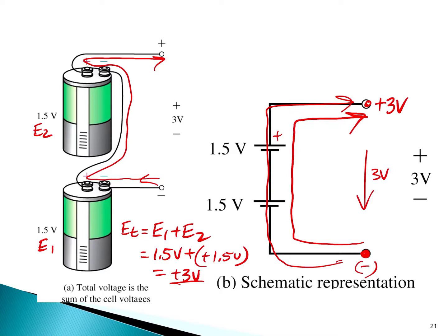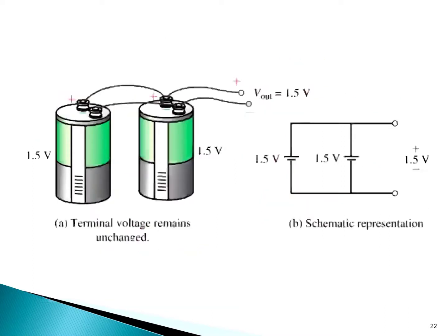Whenever you take a single battery and connect it with others, this is called a battery bank. This battery bank was a series connected battery bank where I used the series connection to increase the voltage value. Now if we think about current in this case, the current would all be the same. So that's one thing we have for a series connection: additive voltage, but the current is all the same.